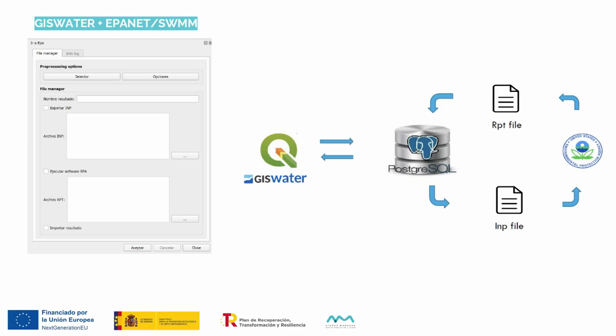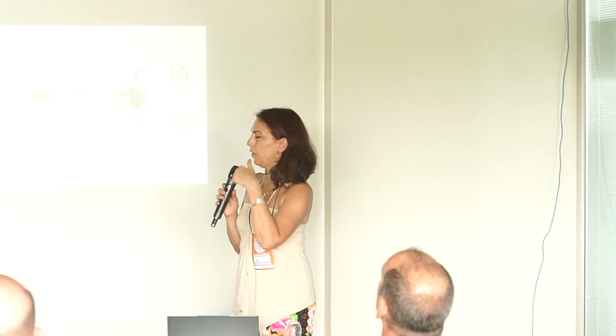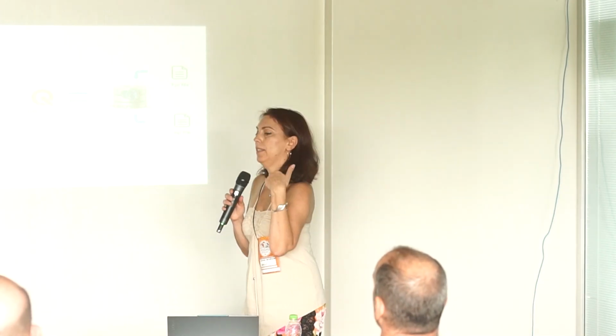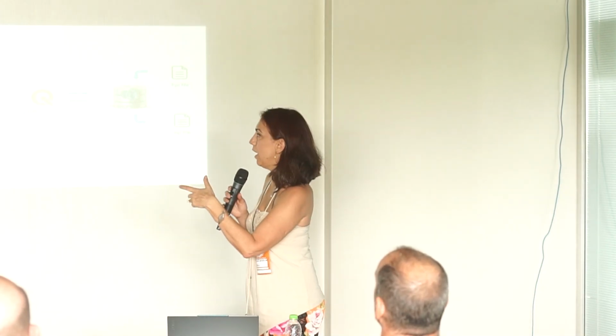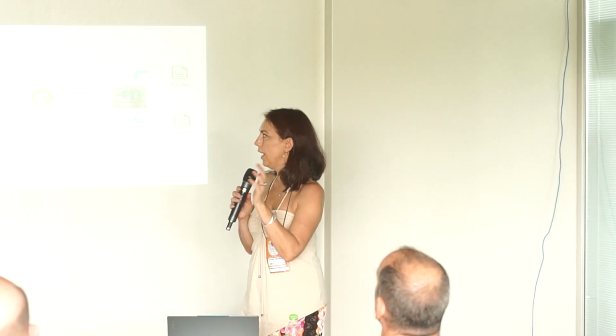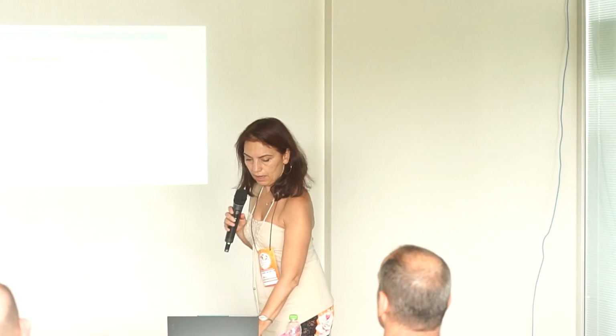Here is the main point: how you create the INP and send it to Epanet. After you have calibrated the model and there are no problems, in just one step you generate the INP, execute it in Epanet or SWMM, and bring back the data.